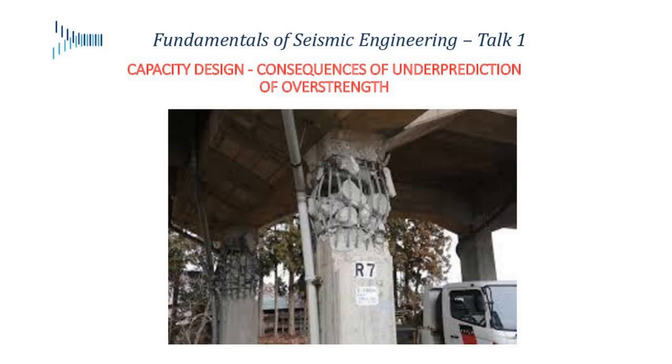I think we used to put number 3 ties at 12 inches, which is probably 12M at 300 when I'm speaking metric. That did not confine your plastic hinge and did not give you any kind of shear capacity, so you couldn't really form a flexural hinge. You ended up with this sort of behavior where your fuse has really just given up.